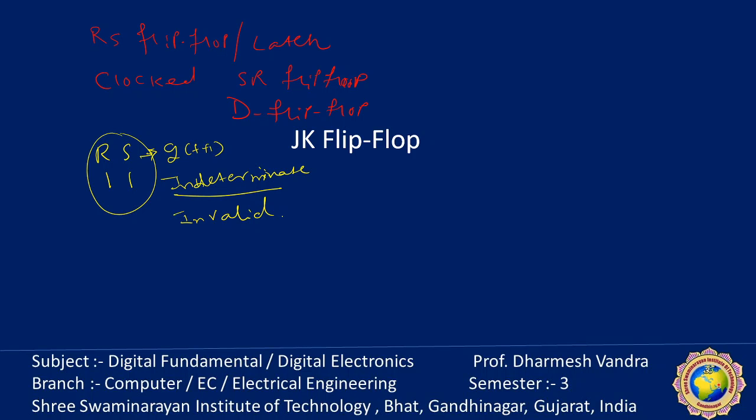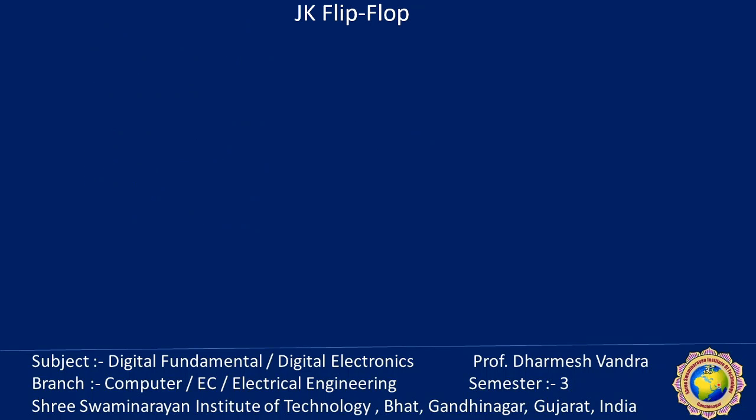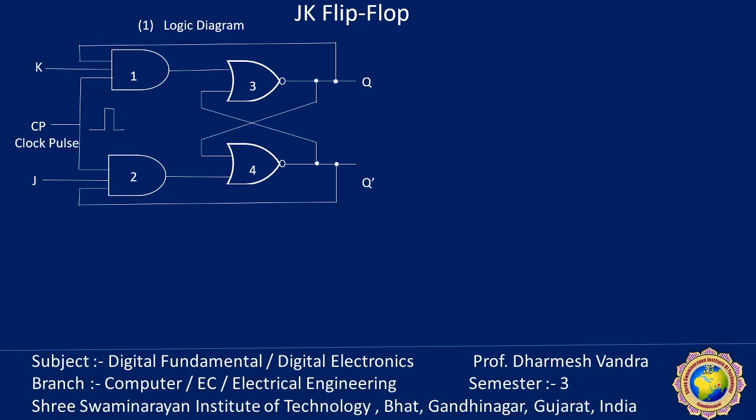So today we will discuss how the JK flip-flop is a refinement of the RS flip-flop, in that the indeterminate state of the RS flip-flop is defined in the JK type. The inputs J and K are like the inputs S and R. J is like S and K is like R. Remember that: to set and clear the flip-flop, J is for set and K is for reset. Let me write that down here.